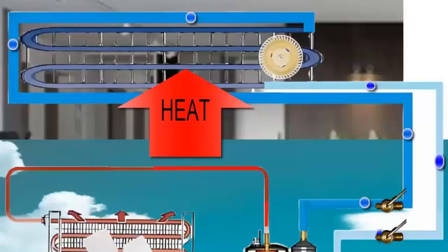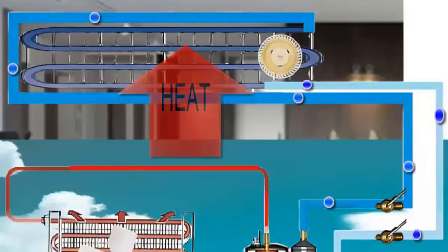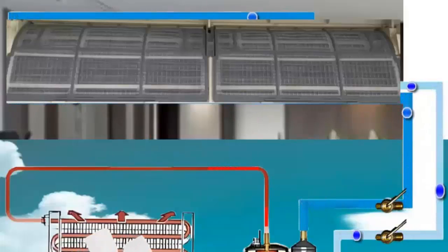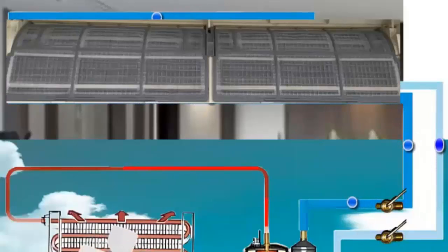10. Problems in the evaporator can be caused by dirty air filters, a dirty turbine, or low fan speed of the turbine.